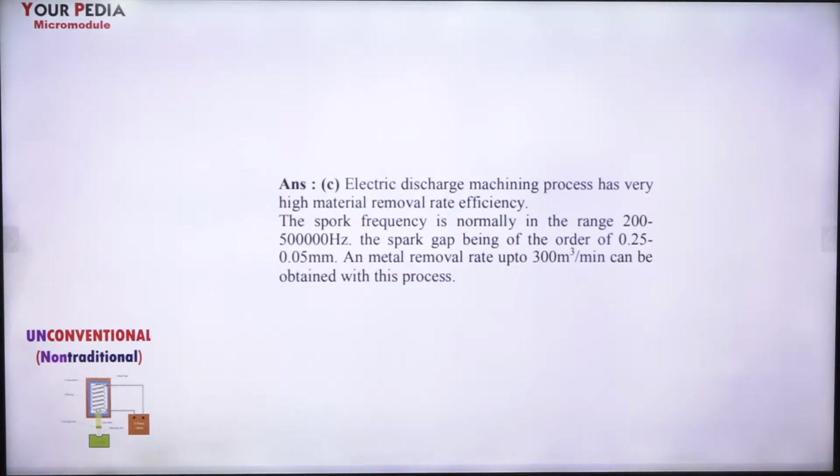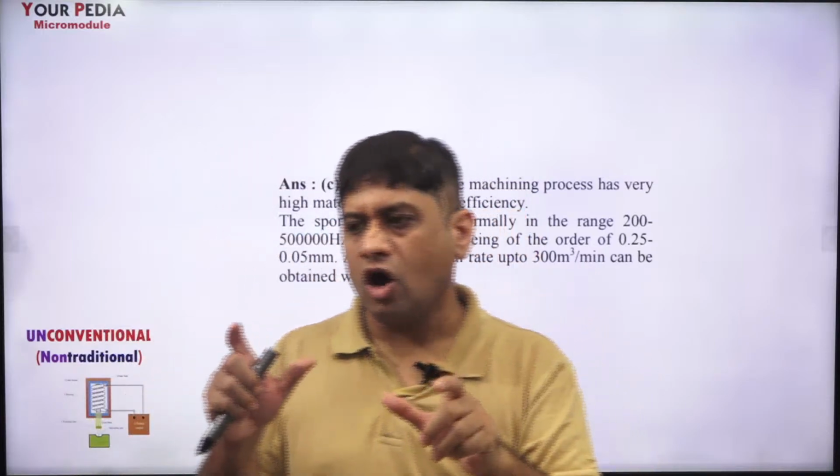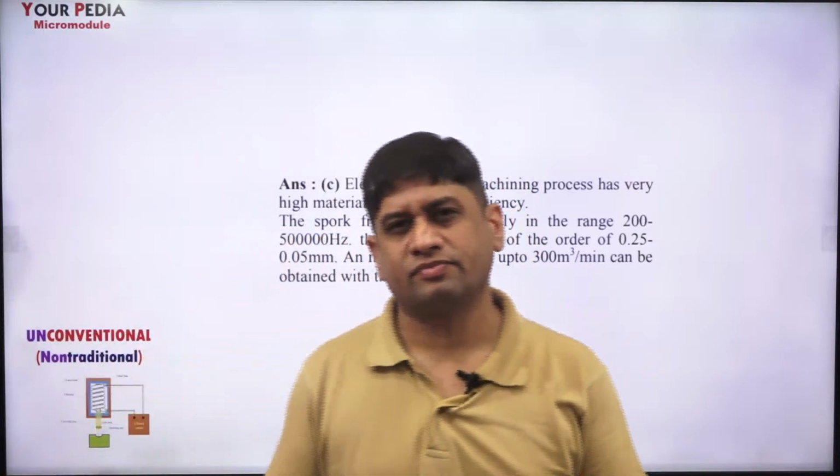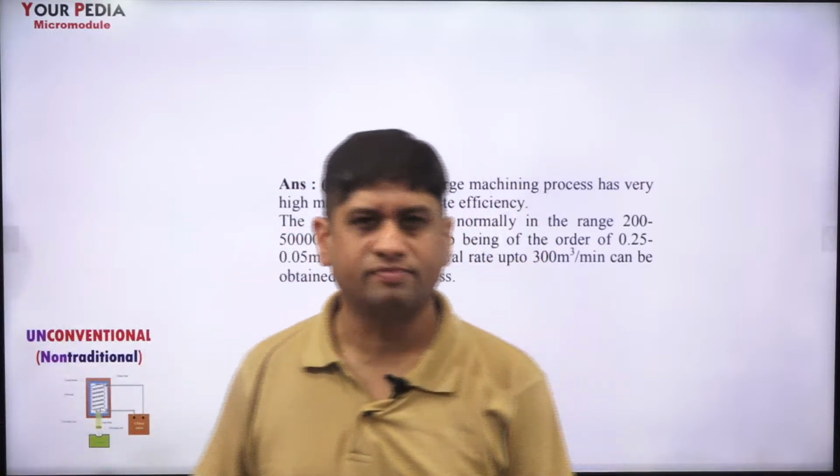See, he is not talking about material removal rate. He is talking about material removal rate efficiency. That means material removal rate is the output, and the input is how much energy you are consuming to remove that particular material. That parameter you have to consider.